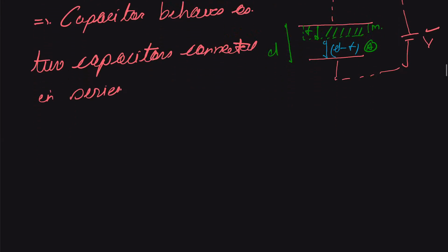And with mica, so we have the first one with mica as the dielectric. Let us suppose the capacitance is C1. So this comes as K epsilon A upon its thickness, which is 2 into 10 to the minus 3.